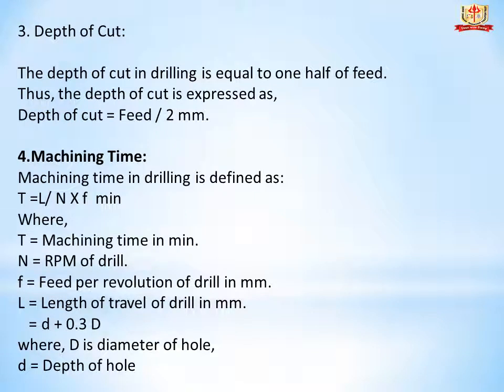Next parameter is the depth of cut. The depth of cut in drilling is equal to one half of feed. Thus, depth of cut is expressed as depth of cut equals f divided by 2, and the unit is mm.